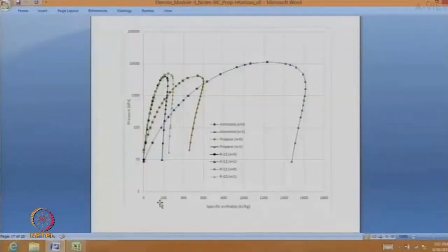And so we could make all these property plots of different substances on this. In the water tables that you see, the specific enthalpy of saturated liquid water at the triple point is set to 0. So I cannot just make that plot and plot h of that on this. They will look fine, but actually they are quite different there. The whole thing will have to be shifted quite a ways out.